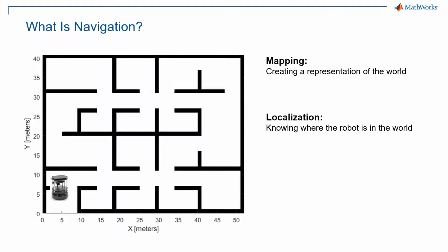The next thing you need to do is the act of localization. So that is to figure out where in the world your robot is. Of course, if you start your robot in a known location, you know where that's going, but then you also have to keep track of it as it moves around the environment. And localization uses the sensors of the robots. The most basic thing would be dead reckoning, which is just counting how the wheels spin to figure out how far you've gone. But there's a lot of problems with that. Often you also want to combine that with your other sensors, like laser scanners or camera, or anything that can give you basically some kind of correspondence with the environment you've already seen.